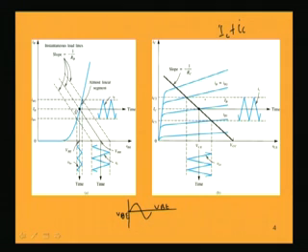Quiescent means silent point, meaning that it is not having any signal in the input. That means it is not having any AC voltage in the input, only DC biasing voltages are there. So, this Q point will be giving you the operating condition of the transistor, and for a particular resistance in the base we have a particular value of IB, and for that particular value of IB, this is the Q point. If we go on changing IB, obviously we will be getting different Q points.